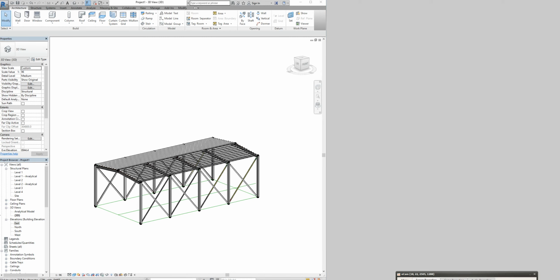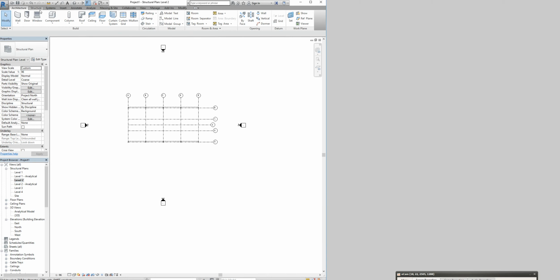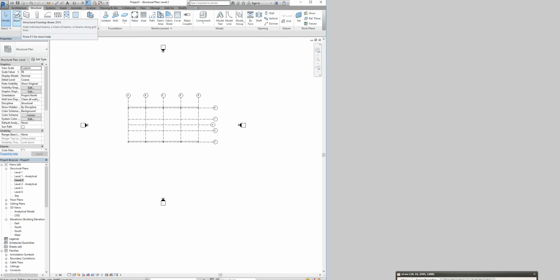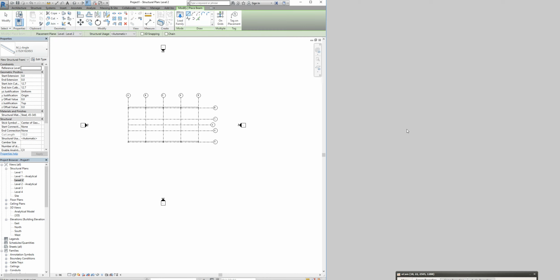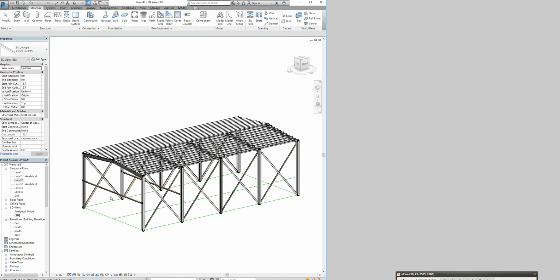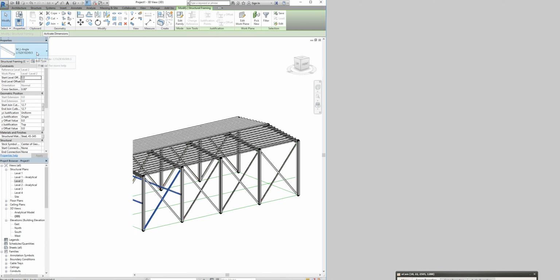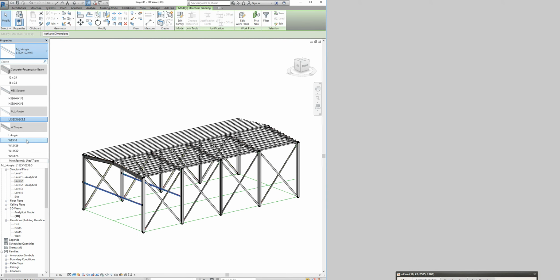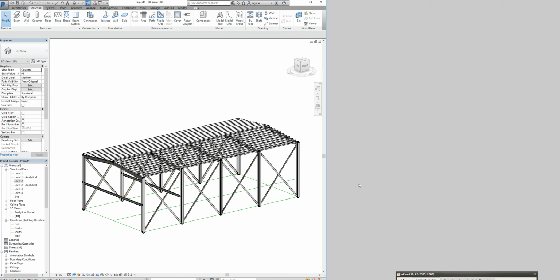Go to level 2, so go to level 2. Select beam tool. We did beams before, so they should know that beam is in structure. So go to beam and create beams along grids A and B. So A and B as shown. So that's one beam, that's the other one. So we create those ones. So that's one. And we're going to create another one. That's two. And we go to 3D view. That's how they look like. They can change the properties if they want, like a different type of beam. I don't mind, just anything. And then next slide.